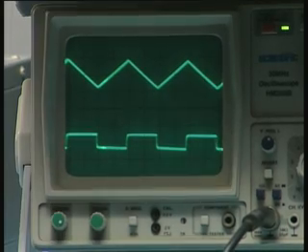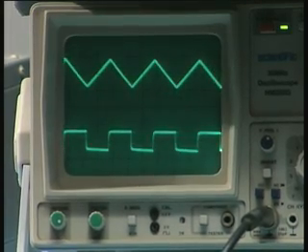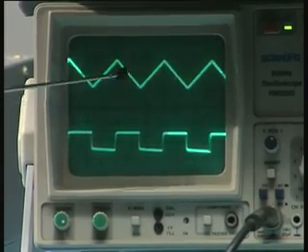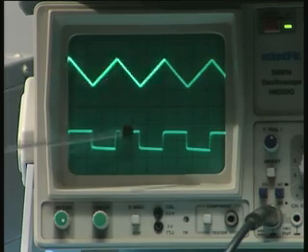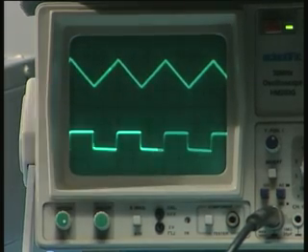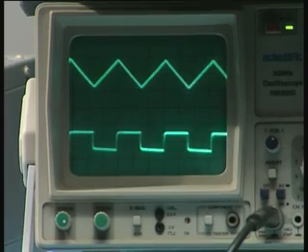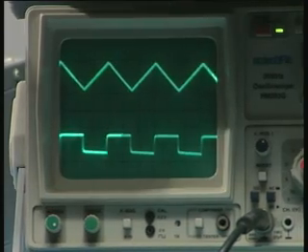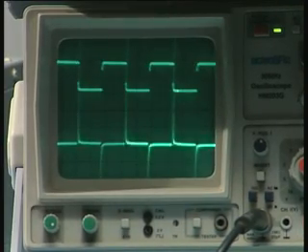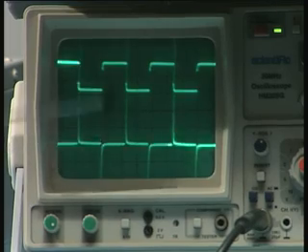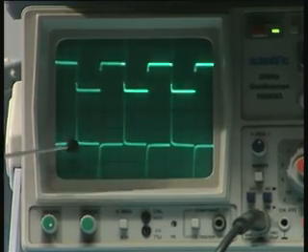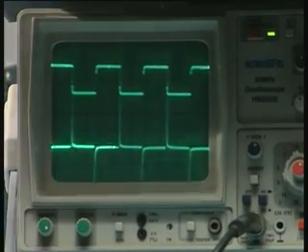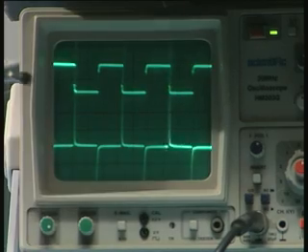Now if I change the frequency, you can see the output is also changing correspondingly. There is a phase factor which you are not able to exactly see, but you can see the triangular wave becomes a square wave when I apply it from a function generator. I also mentioned what would happen if I apply a square wave at the input of the amplifier. Therefore I now change the input to a square wave, and you can immediately see the two sharp pulses corresponding to the transitions high to low and low to high. That corresponds to the differentiation of the square wave.